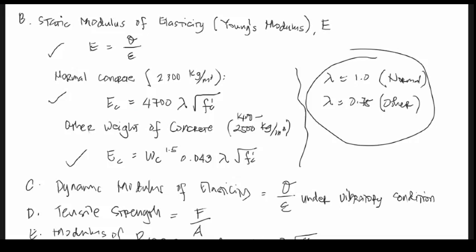It can also be other formula, that is moment multiplied by the distance from the centroid up to the effective depth all over the inertia, or MC over I. That is the bending stress, kung maalala ninyo. So again, pakipicturean na lang, tapos we can delete. So those are other properties of concrete.